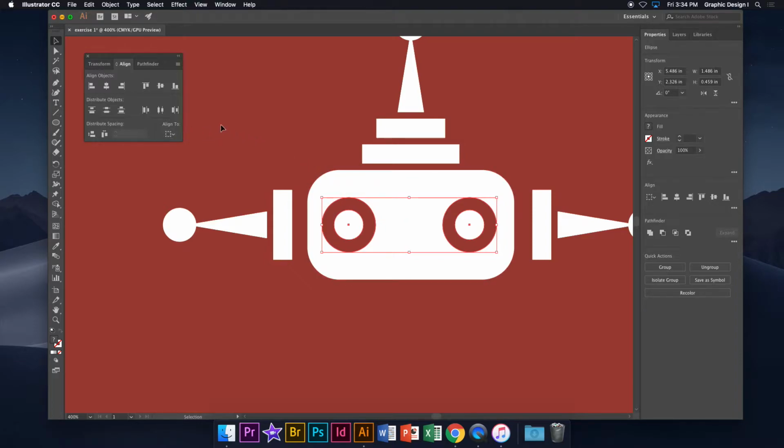All right, so first what I'm going to have to do is go to the Align Tool button on the tool palette right here, and I want to align it to the selection. Now, in order to align it to the selection, I have to tell it what the selection is. And the selection is, I'm going to click on this guy, and then I'm going to shift click so I select this guy as well. And now when I vertically align it, notice what happens. It now shifts. And now that thing is perfectly aligned.